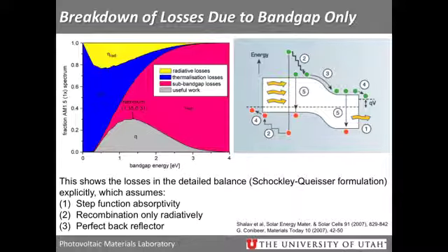The third part is radiative losses. Those are quite small and more of an issue for smaller band gap. Because you're absorbing so much more light, your solar cell heats up a lot quicker, and then you have your solar cell acting as essentially a black body radiator. And so you'll lose some efficiency just based on radiative effects from your solar cell into the surrounding atmosphere.